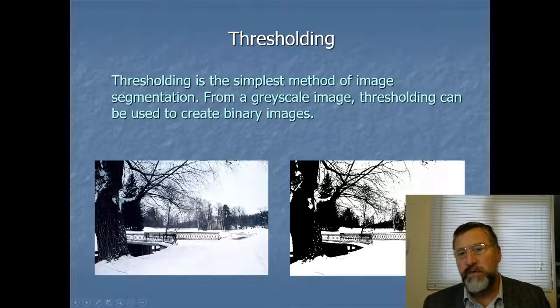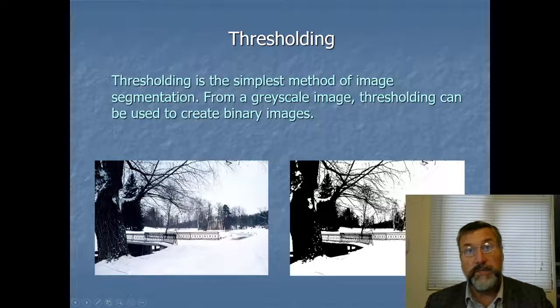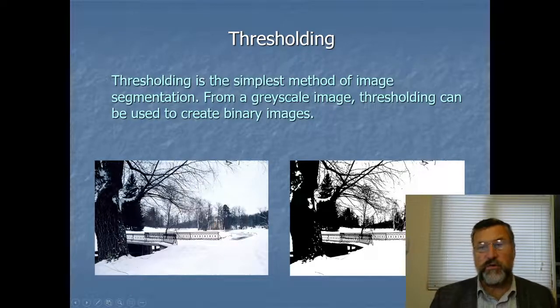The point is that if you've got a binary image, you need a binary palette to display it. If you're inadvertently using a grayscale palette, which I remember doing years ago, getting confused with a black image coming up, that's because the grayscale palette interprets the 0 as black and the 1 as more or less black, if you know what I mean. But you need the binary palette, and you need to tell the VI that's displaying it, WinDraw, you need to feed in a binary palette into it. This will all become straightforward when you do it with LabVIEW.